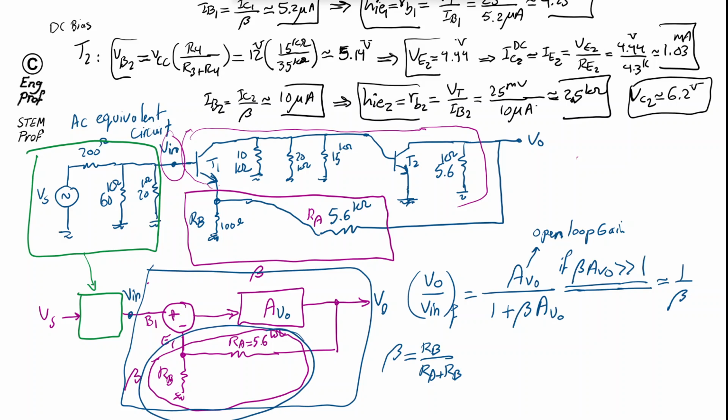So that is effectively the feedback voltage VF across RB, divided by the output voltage that is sampled. Plus minus V out comes here, and the feedback voltage arrives at the emitter and subtracts from the input voltage. Therefore, I can say this one is 1 over 57.